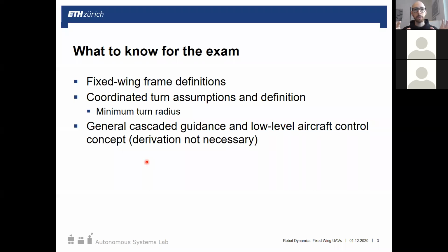Basically having the high level taken care of, position control, giving and controlling airspeed as well. So altitude and airspeed, for example, on the longitudinal axis, lateral position control on the lateral axis. These then give those attitude references to our low level attitude controller. Again, those are in the previous slides, so I won't cover those too much today.